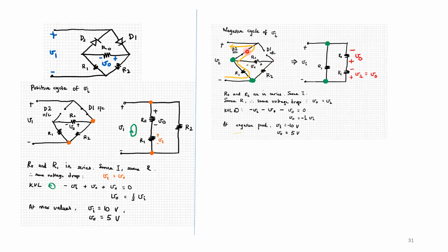There are no other connections here because this is an open circuit; D1 is non-existent in this case. But the node between R out and R1 is also connected to the short circuit of D2, which is then connected to the positive terminal of the supply V in.